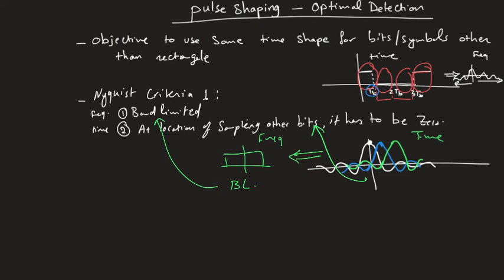So remember that what's transmitted in time domain actually are those shifted sincs. Each one of them represents a bit. Again, practically you cannot send the sinc function because it expands all the way to infinity, but you will send a reasonable duration, which means that in frequency domain it will not look like this exactly, but it will be slightly different, but that's fine within practicality conditions.